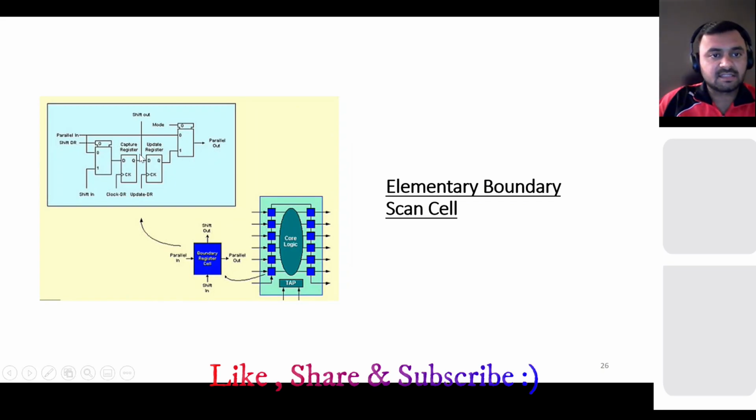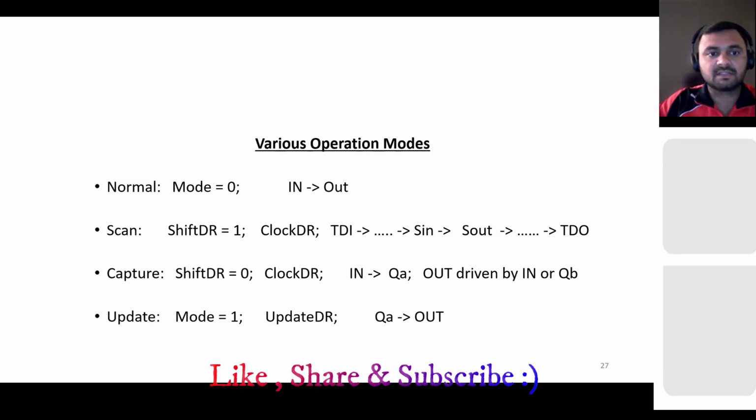So this is the basic structure, how it works. There is a capture register, there is an update register, and there are 2 muxes. Basically this is a mux. In IEEE they use this symbol for the mux, where this mode is the select line, and you select between 2 different signals, and here the shift DR. So this mode, shift out, capture, shift, these are all signals the TAP generates, but this parallel in, parallel out is your device functional signal from the top. So basically just a basic operation.